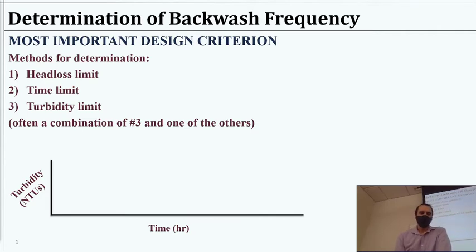And for turbidity, if we think about a system that has some rinse period, if we had a rinse at the start of our cycle, and then at the end somewhere we'll take it off and backwash, and then we end our cycle, the turbidity will probably, and let's imagine we have a cutoff limit where if it goes above this level, we have to stop.